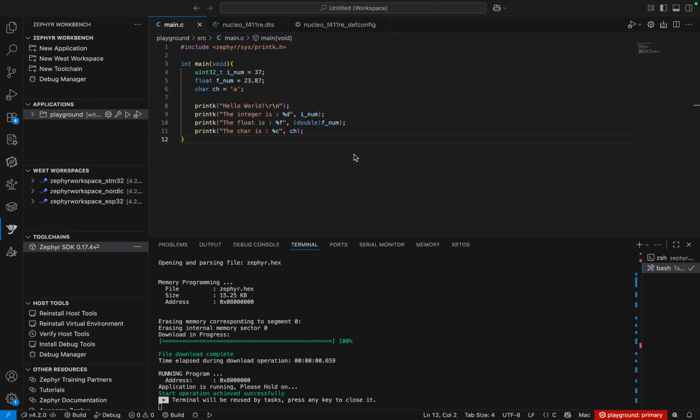And because of this serial communication link between the two, you can write something from your microcontroller and it's going to push that data through the link onto your host computer. And so there has to be software on your host computer side that is able to take this information from the serial communication and also present it to you. And this is what has been leveraged in Zephyr to provide the two different approaches I'm going to teach you about.